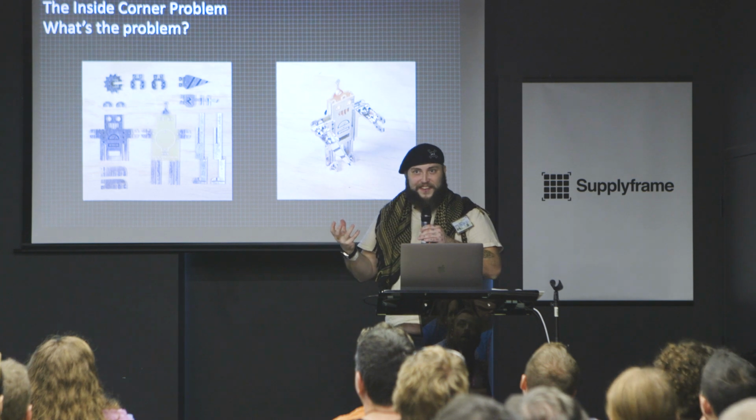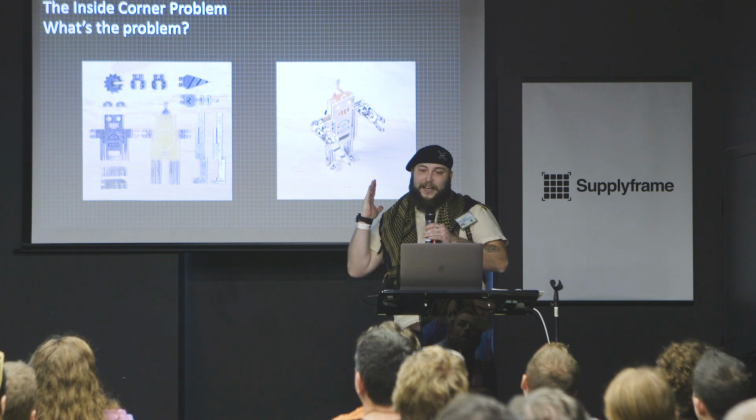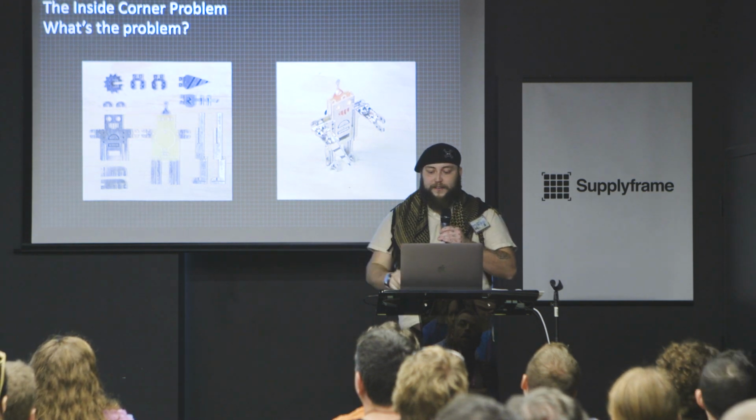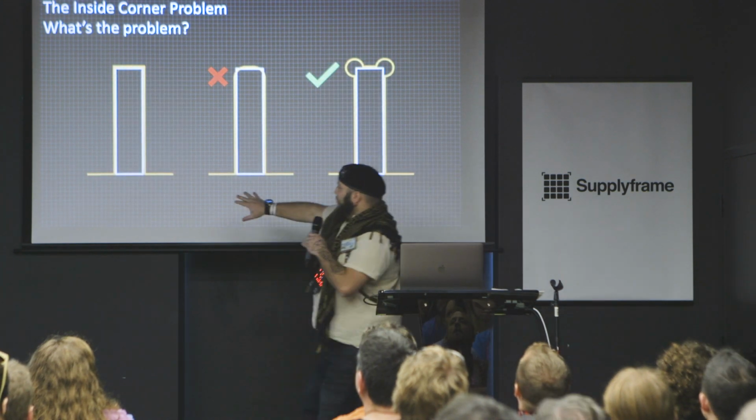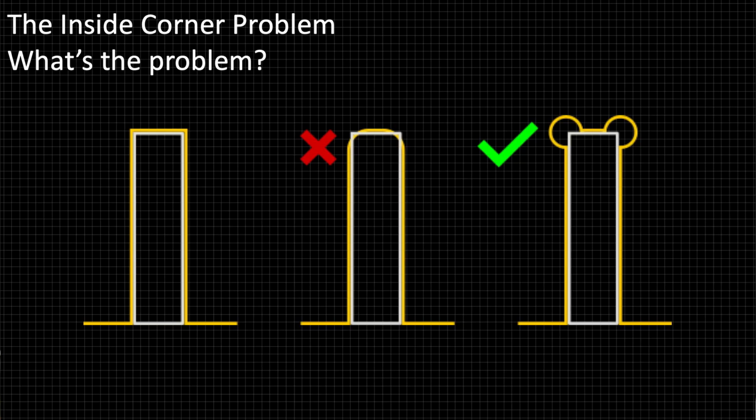they exist in the world and have dimensions. So if they're bringing that round end mill into a corner, it doesn't actually get into the corner, and you end up with something like this, where this is beautiful, this is what I designed, and this is supposed to work, and then, oh no, you got this round corner, and now this isn't gonna fit all the way in there.